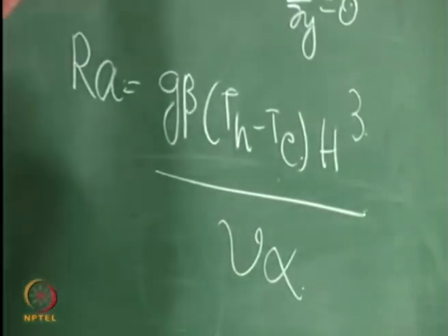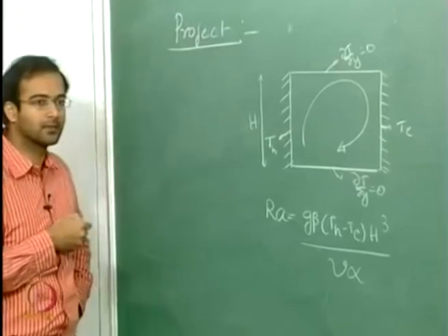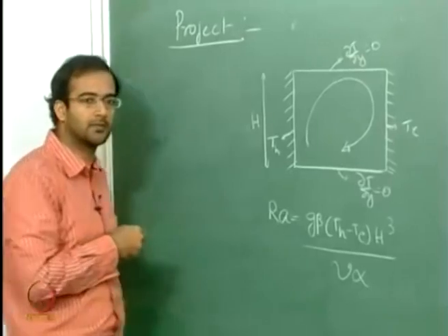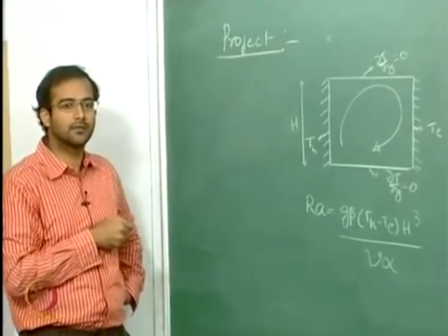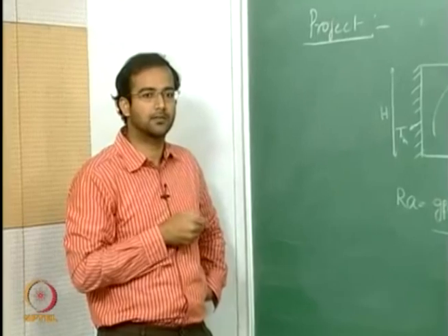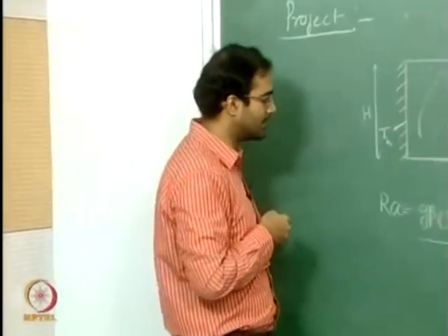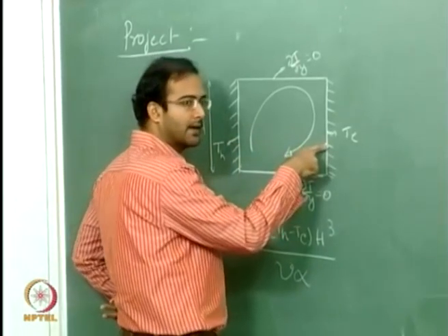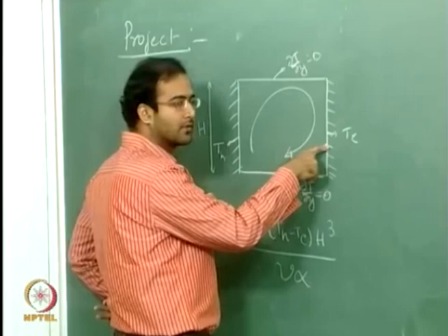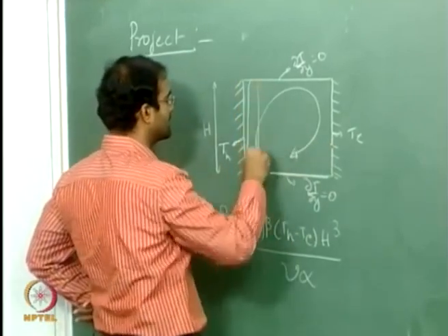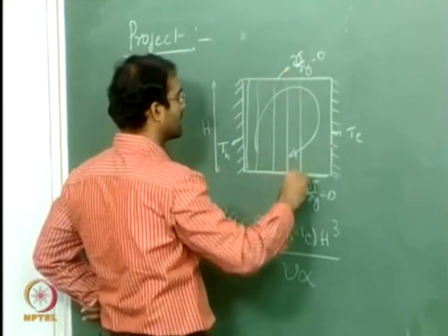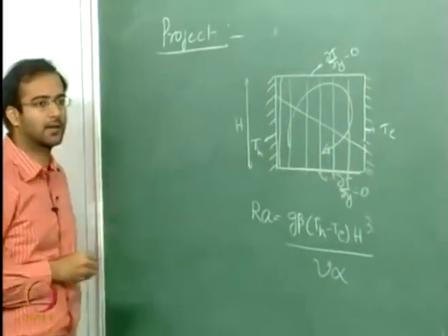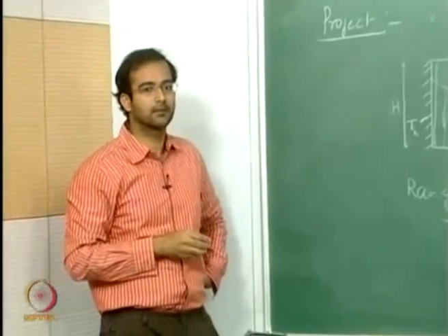will give you the strength of the convection which is happening. So you can see that the buoyancy force is linked to the temperature difference. The higher the temperature difference, the greater is the density difference, and that creates the convection patterns to be stronger and stronger. So initially for small delta T's you will find the convection pattern is very mild and it will be mostly conduction. If you look at the isotherms, you will find that the isotherms go like this almost, and there is a linear profile from the left to the right, that is indicating that it is the conductive mode